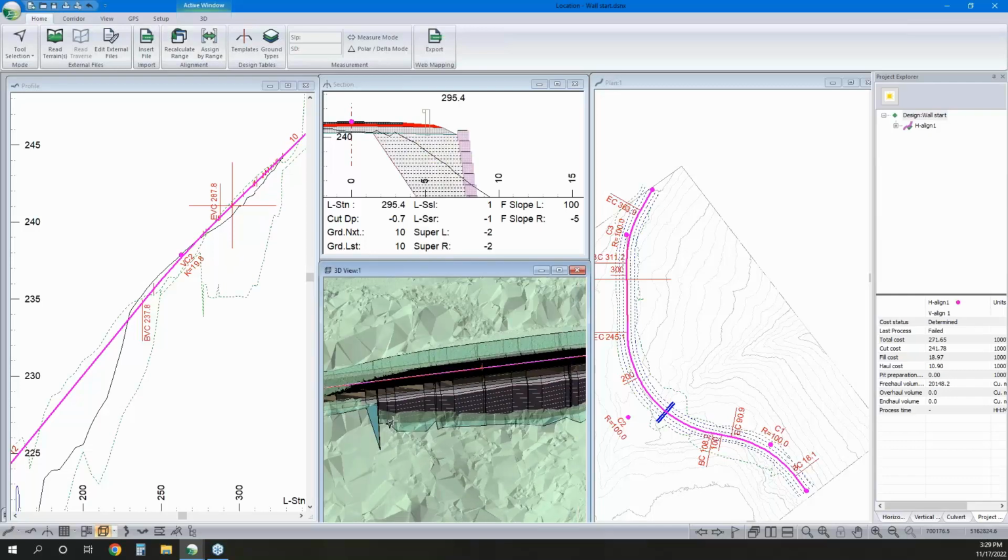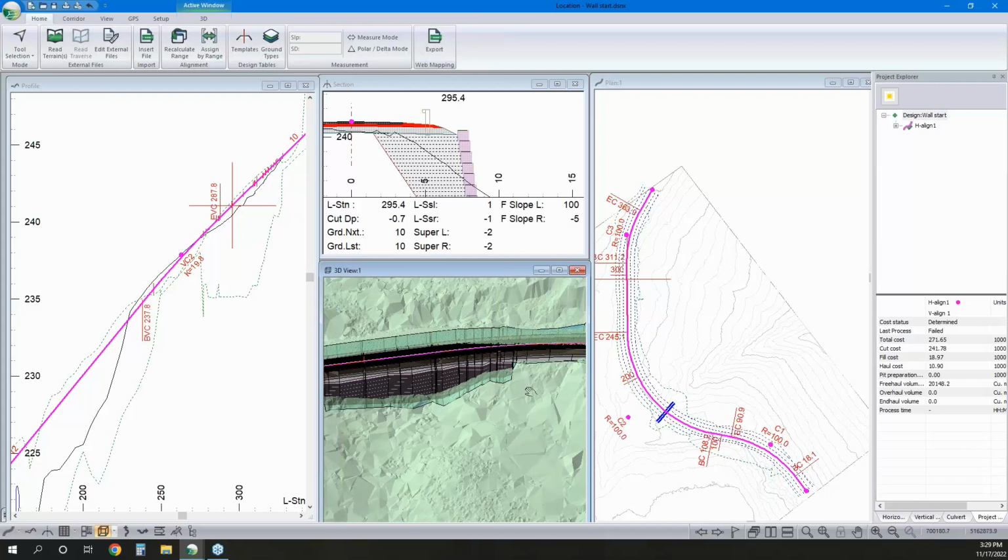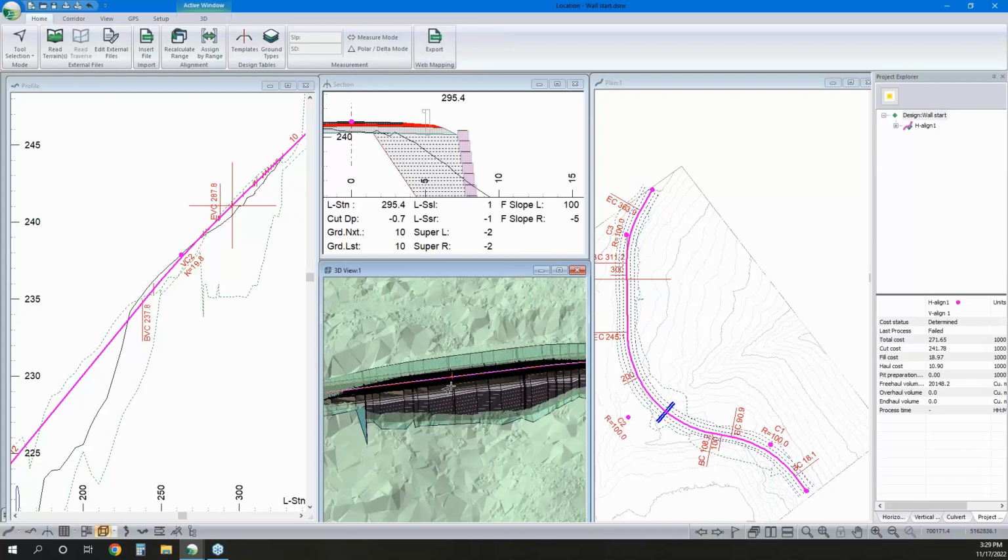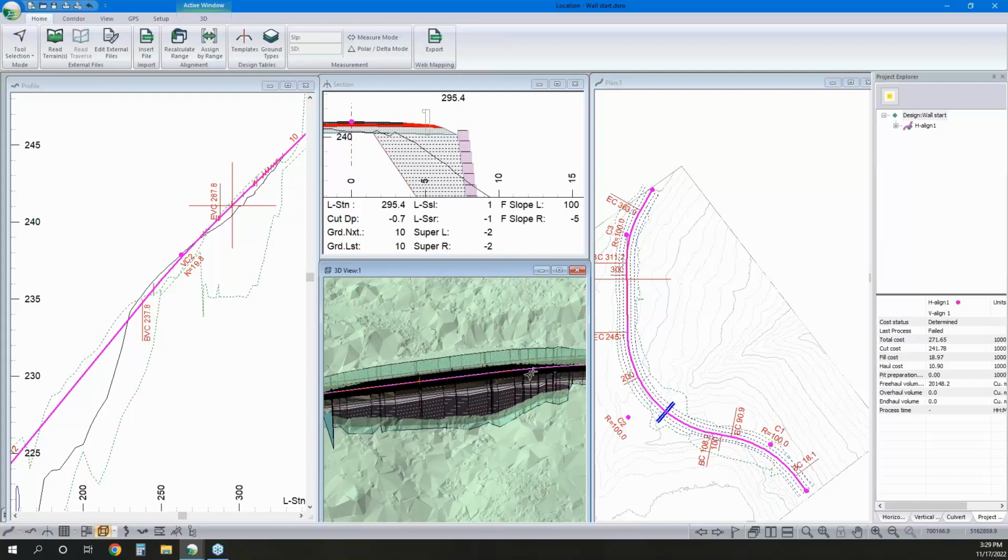So we have that. Now, a few things that are going on here. One, I'm going to just increase how frequently we're creating cross-sections through this portion, just so I can see those steps a little clearer rather than these long-ish interpolations.